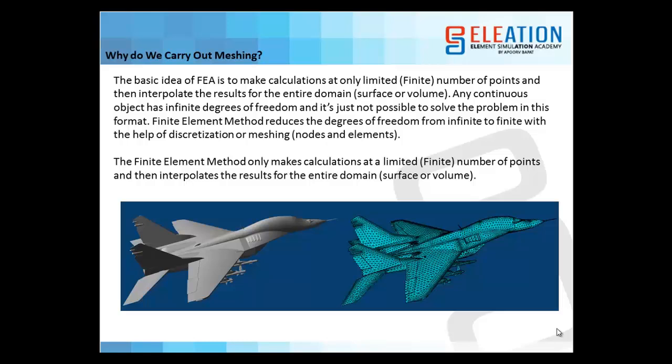So any continuous object has infinite degrees of freedom, as you can see here on the left hand side of this model, where the number of calculation points is infinite. So it is just not possible to solve the problem in this format. While the finite element method reduces the degrees of freedom from infinite to finite with the help of discretization or meshing,